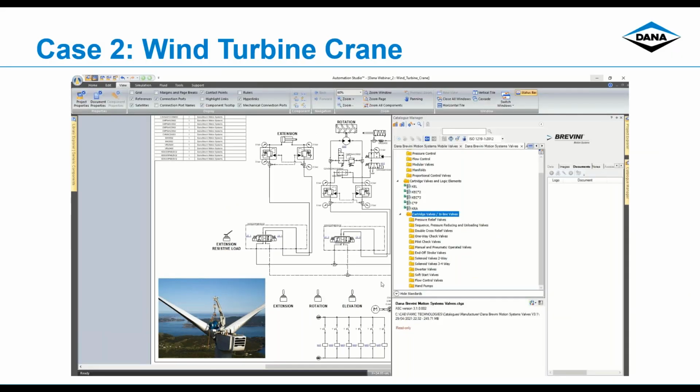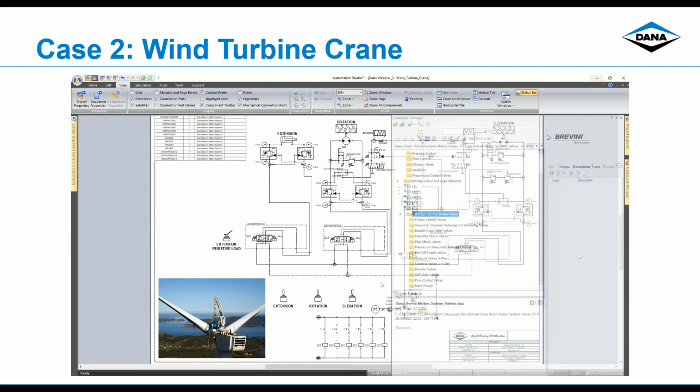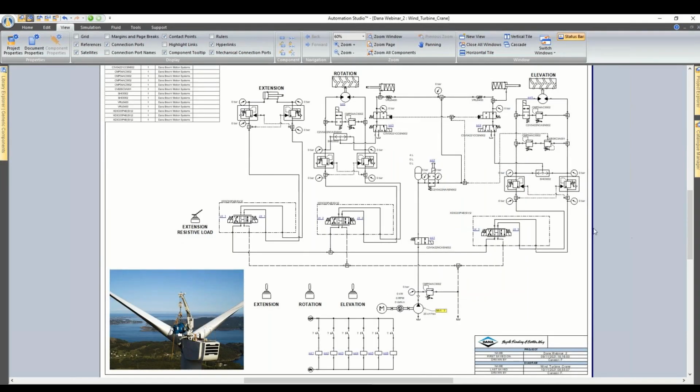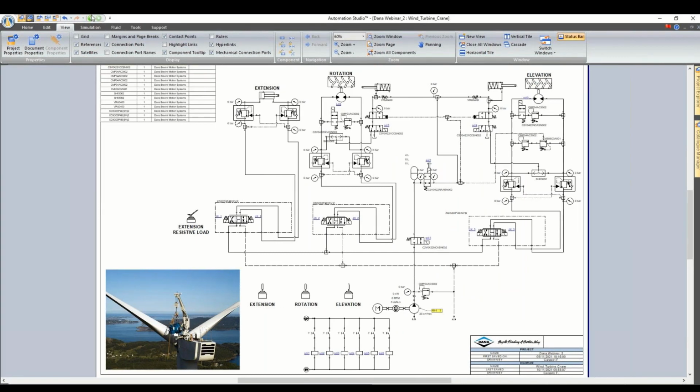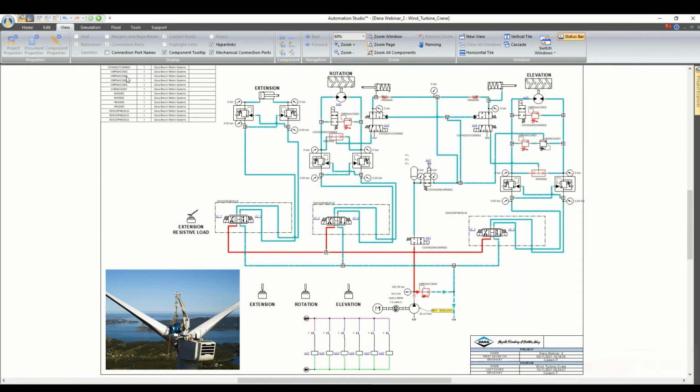And now let's move to the second video, where I want to show you the simulations, with the possibility to first of all activate some safety functions. The first one is to close solenoid 2, close solenoid 1, and then reopen solenoid 2 in order to allow the accumulator to be filled for the safety function.